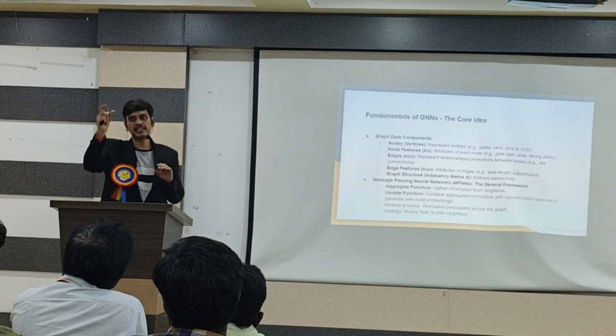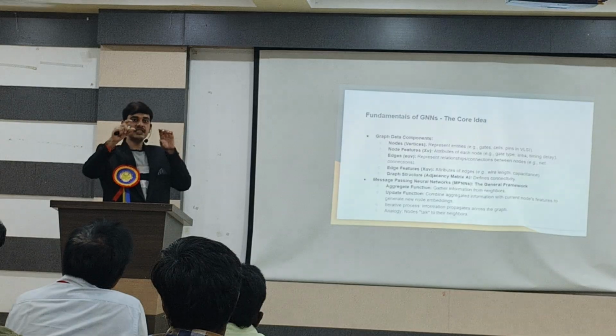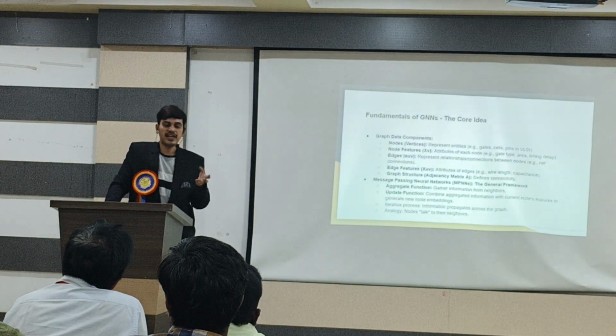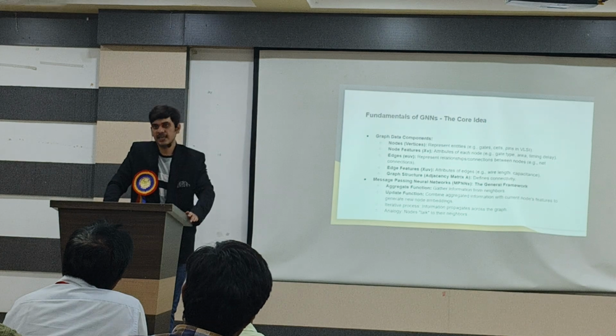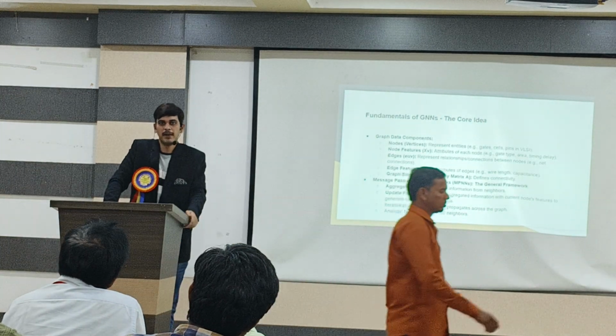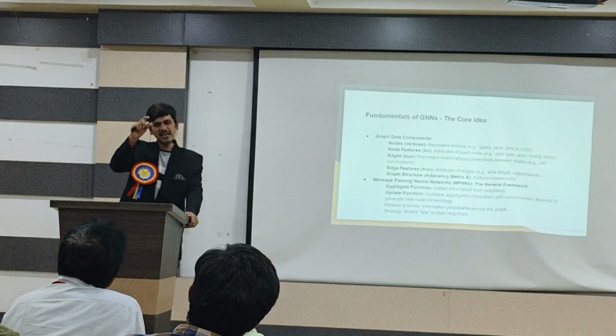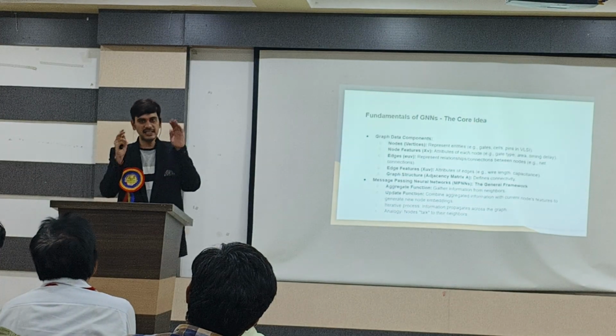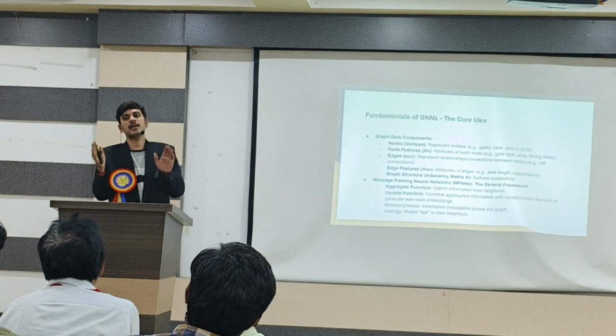Because there is a capacitance in there, the equation will have it, so based on these two, delays will be calculated. Because in the timing report you will see that, for example, when I am analyzing the timing reports during my project, D4 is connected to D6. The same cell has a 50 ps delay in one case and a 100 ps delay in another.